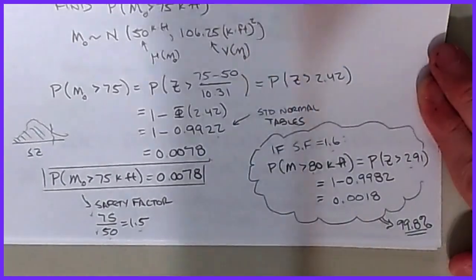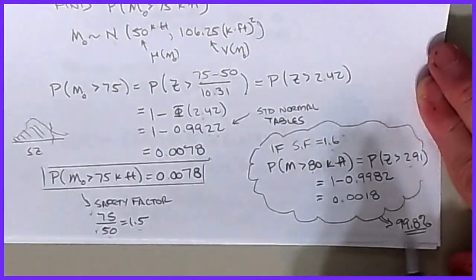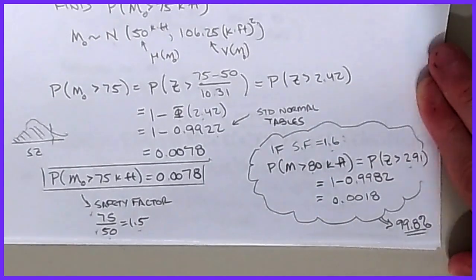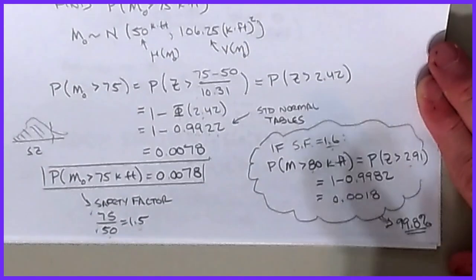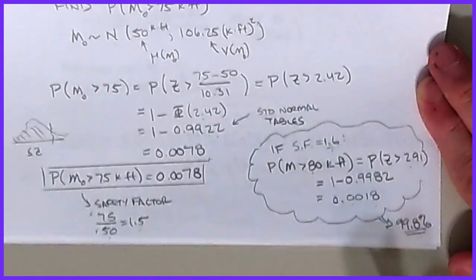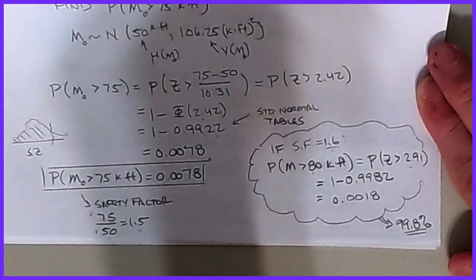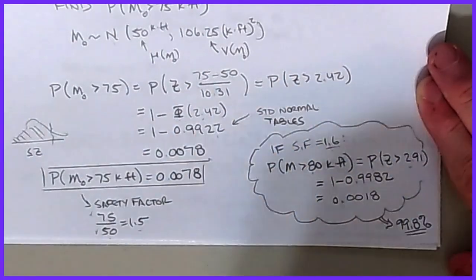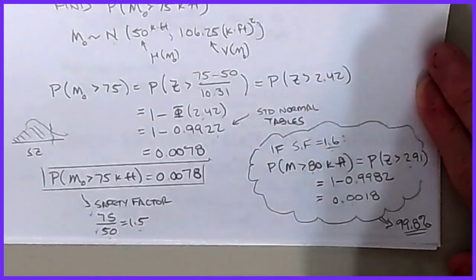Now, there are some other things that we do to make sure that we still have the safety we need, but that's a pretty high probability that you're going to be less than that number. And so it's kind of interesting that that's where that value starts to come from: a statistical analysis of a simple statics problem like this. They say a live load, which is a load that can have high variability, it's not constant, has high sigma, so they can calculate that quantity.